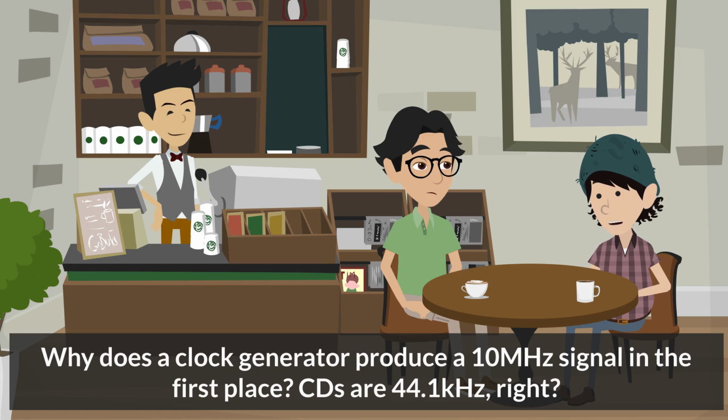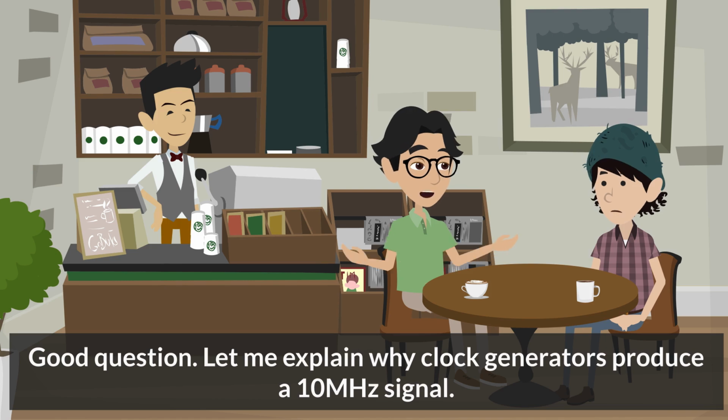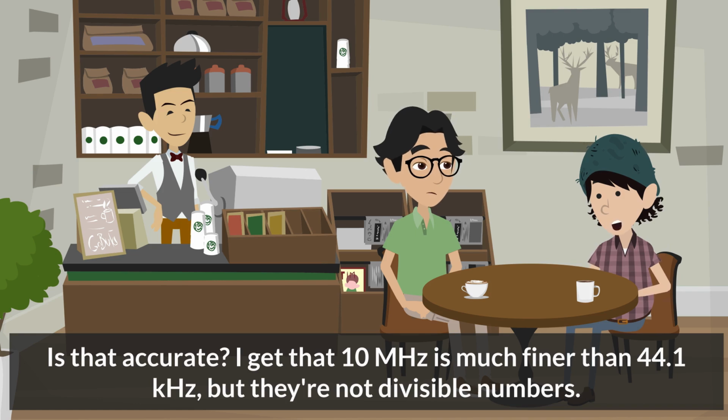Why does a clock generator produce a 10 MHz signal in the first place? CDs are 44.1 kHz, right? It seems completely unrelated to 10 MHz. Good question. Let me explain why clock generators produce a 10 MHz signal. In the audio world, a 10 MHz clock and a 44.1 kHz sampling frequency seem completely unrelated at first glance. In reality, 10 MHz is merely the reference frequency, and the 44.1 kHz clock is derived from it. Is that accurate? I get that 10 MHz is much finer than 44.1 kHz, but they're not divisible numbers.